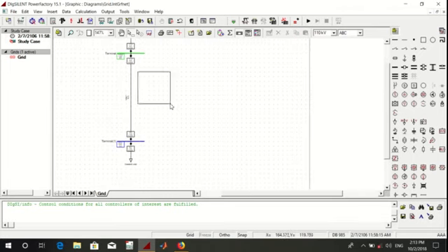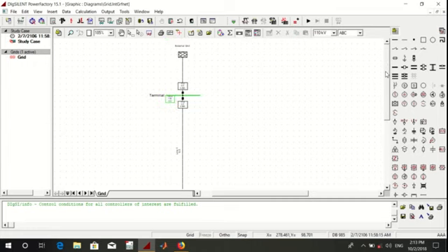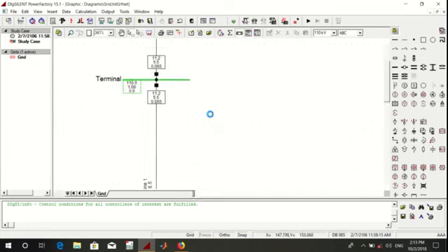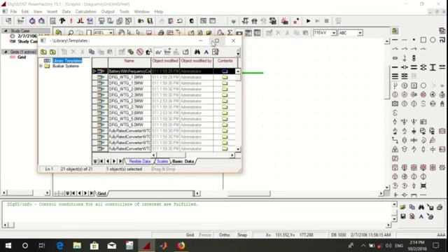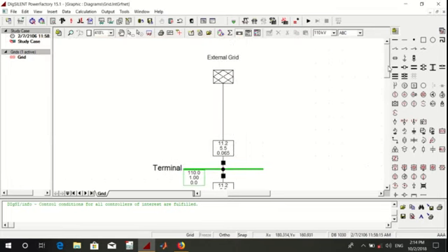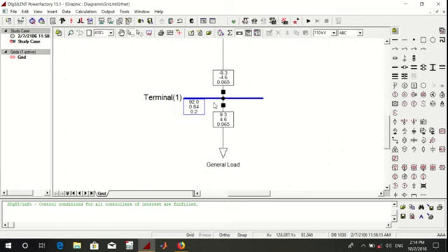Now we go through our system. Now you can observe from here the voltage that we have defined at the terminal, 110 kV and 1 per unit. This is the angle that we have defined. For the other bus bar that we have defined, it was 110 kV, rated, and per unit we have selected, for the definition of each bus bar.